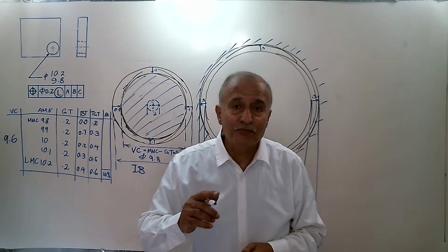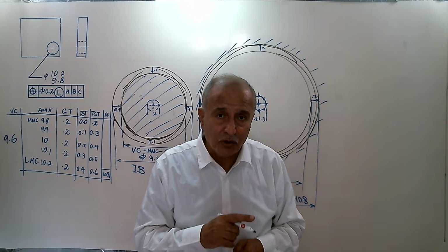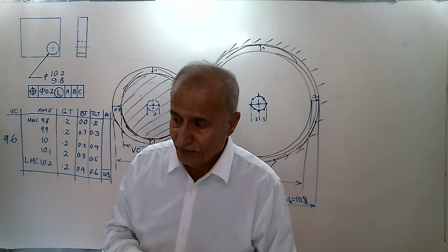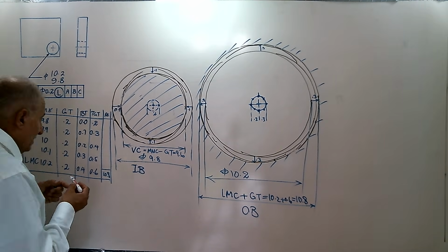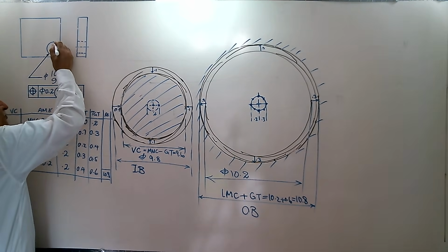And the most important point here, when designers use L for the hole, they mean material sufficiency. What does material sufficiency mean? Look at this design here. Material sufficiency when we use L means we are worried not about assembly, we are worried about the wall thickness.